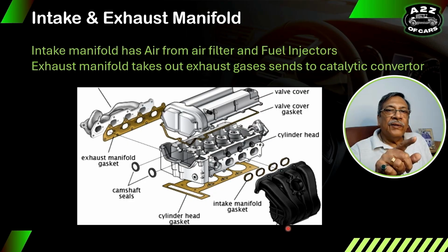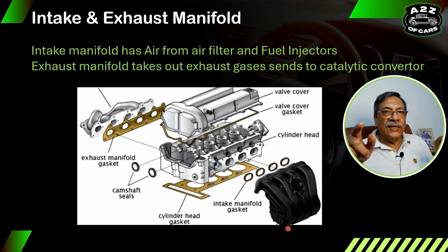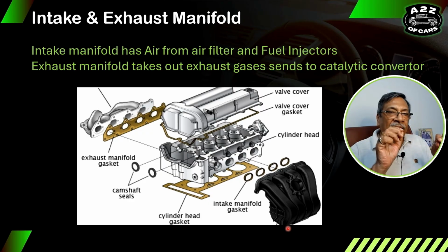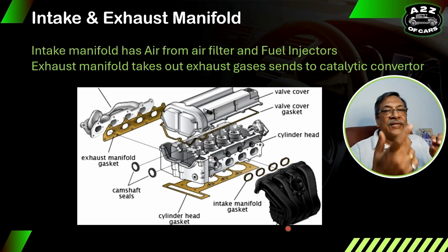And for every cylinder, there is a pipe going, right? So the air is already there, and as and when the intake valve opens, fuel will be injected through the injectors, and from the valve the air fuel mixture will be going inside. So that is how the intake manifold works.